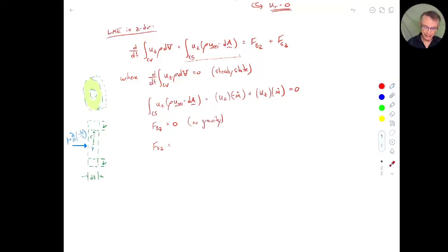This is this idea again: if the pressure at the center is P, I start with that pressure. I see how pressure varies as I move in the z direction because I'm going from the center to the left. That's in the z direction. And I multiply it by how far I've moved in the z direction, which in this case is minus dz over 2. And then I can do the same thing on the right-hand side.